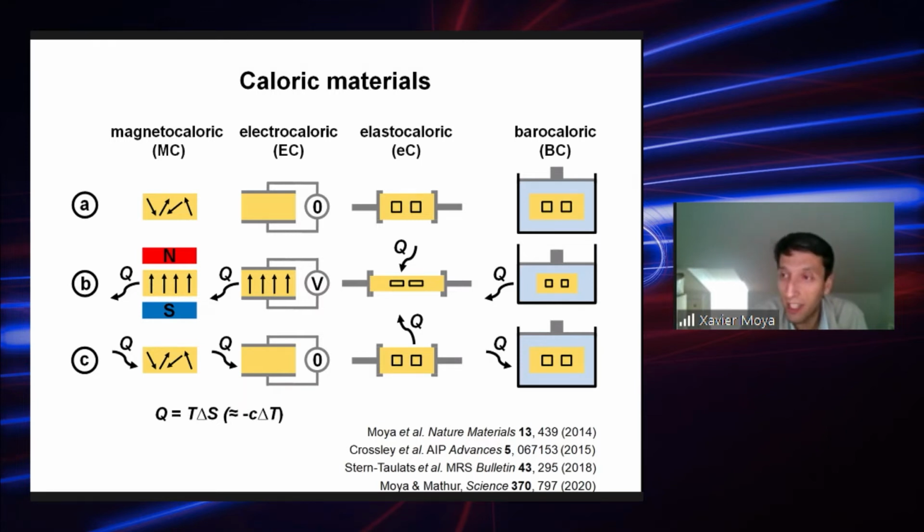Now, in terms of magnetocalorics, if you want to make an efficient application, you need to use a permanent magnet. And typical permanent magnets that are not really huge and not very expensive, normally give you 1 Tesla, 1.5 Tesla magnetic field, which means that the best magnetocaloric materials normally give you a temperature change in the region of 3 degrees. So it's relatively small, so it's not so easy to make an application.